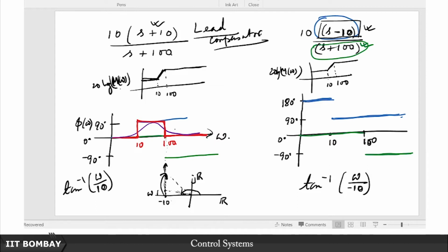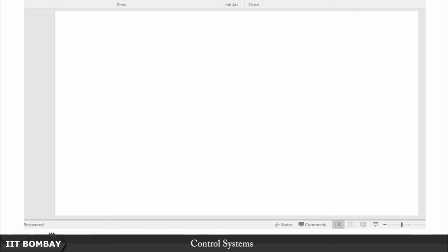So you can also see the justification of the lead compensator name from the Bode magnitude and phase plot as well. So all this we understand. The moment this fellow with a 0 in the right half plane comes in, it kind of spoils our party. All this understanding that we have about the lead compensator, the way the phase plot is supposed to look, all of it changes.